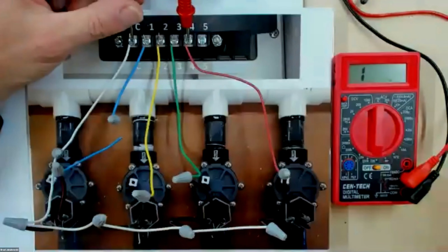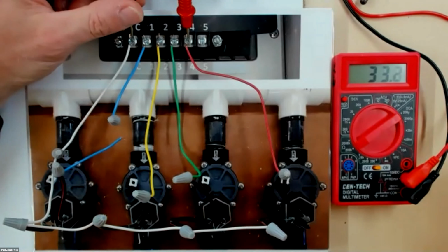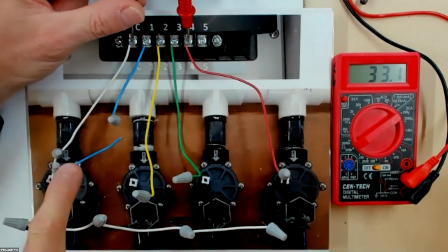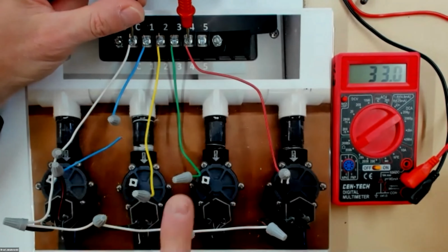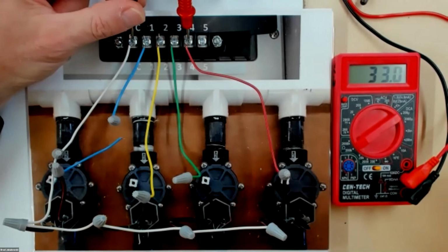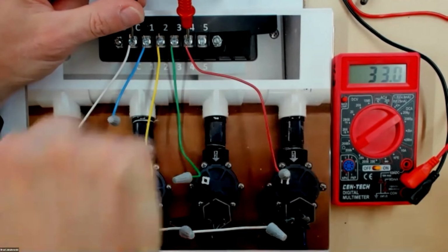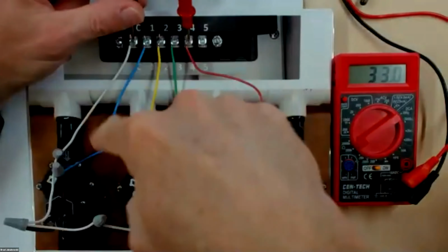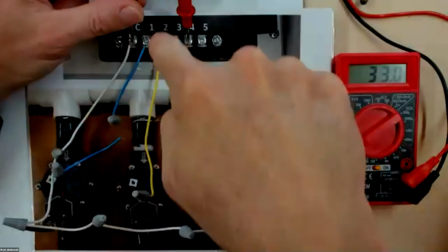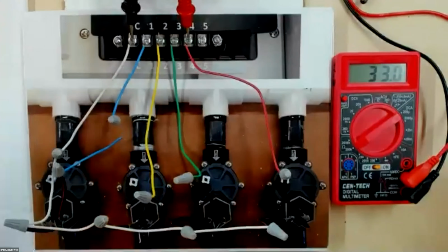And then we could finally move over to station 4. We have an open, or if we switch it over to here, we have 33,000 ohms. So station 1 is not working correctly, but stations 2, 3, and 4 are operating as they had been before. So we could definitely isolate it. It's not a common wire problem, but it's a station wire problem, and only with station 1. Those are the kind of readings that you could get.